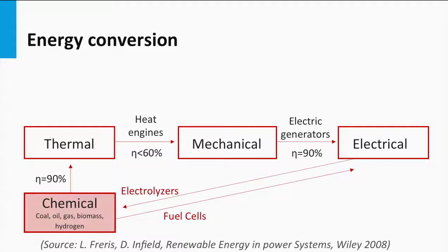A regenerative fuel cell operates in the reverse mode and converts electrical energy into chemical energy. Such an operation is called electrolysis, and the device operated in such mode is called an electrolyzer. Typical conversion efficiencies of hydrogen electrolyzers of 50–80% have been reported.